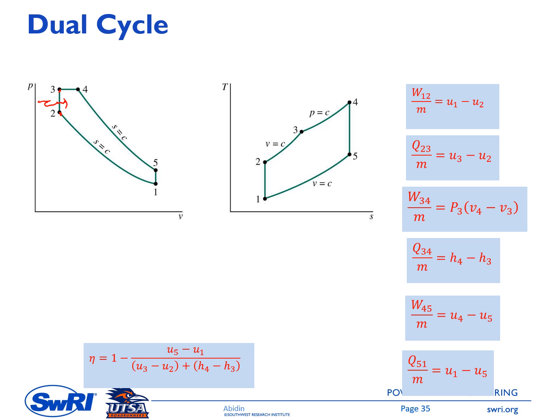Okay, we have heat addition here. Let's say I call this Q1. And then you have another heat addition here, it is Q2. That's why it's called the dual cycle. So the heat addition occurs in two processes: a constant volume process and a constant pressure process.